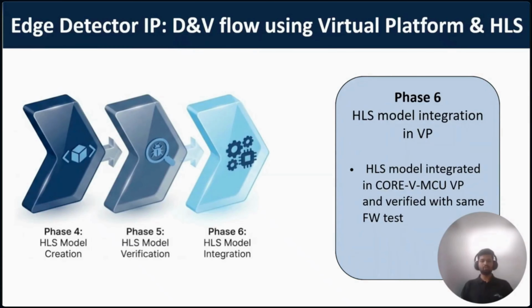Finally, in phase 6, we perform the ultimate system integration. We returned to the core VMC virtual platform and replaced our original TLM model with the HLS implementation and its adapter. Because we reused the same software application for validation, we could confirm that the actual hardware accurate implementation performed exactly as intended within the full SoC environment. This seamless plug-and-play transition significantly reduces our integration risks.